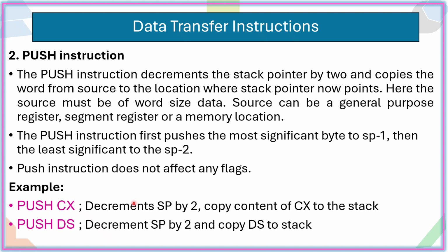Most importantly, the push instruction first pushes the most significant byte, MSB, to stack pointer minus one, then the least significant byte to stack pointer minus 2. Push instruction, like move, is also not going to affect any flags. The examples of the push instruction are given here.